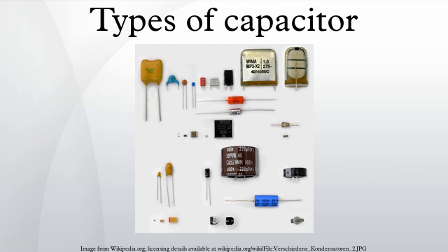The comparison is easy, because the manufacturers use standardized case sizes or boxes for different capacitance voltage values within a series. In reality, modern capacitor series do not fit the theory. For electrolytic capacitors, the sponge-like rough surface of the anode foil gets smoother with higher voltages, decreasing the surface area of the anode. But because the energy increases squared with the voltage, and the surface of the anode decreases less than the voltage proof, the energy density increases clearly.